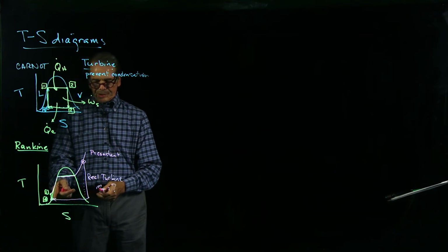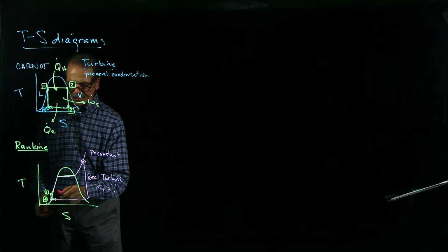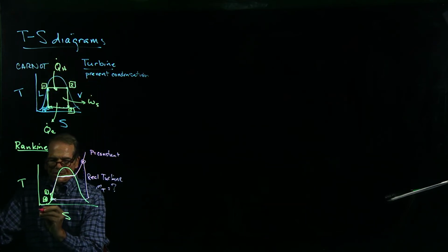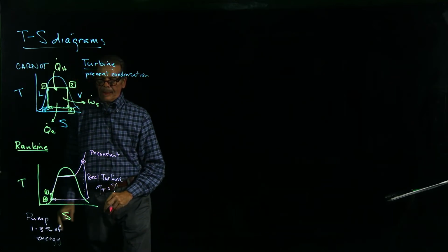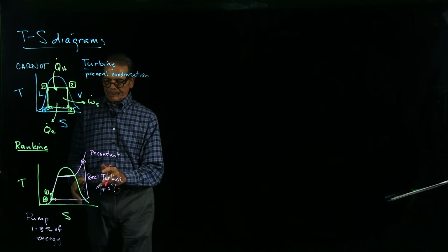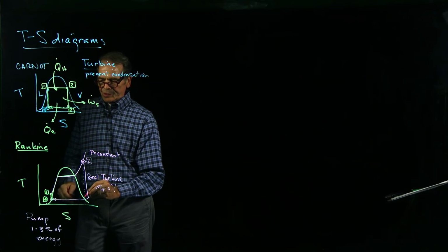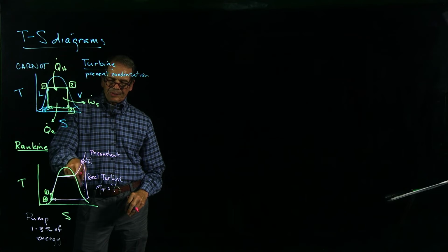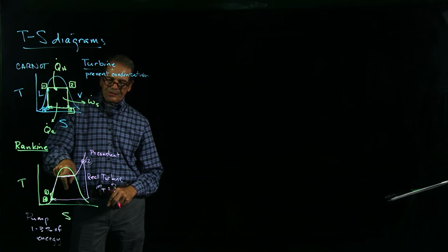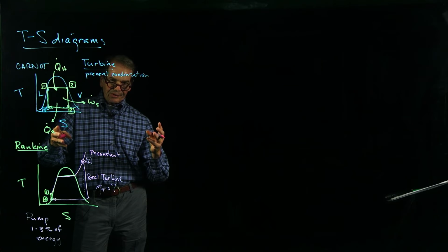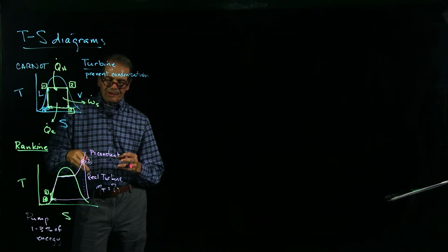The pump. We're going to put some energy into the pump, but this is typically only about 1 to 3% of the total energy in this system. Okay? Well, that's pretty good. Let me label the points. This is 2. So in the furnace, we're going to pump it up to a high pressure. These 2 pressures are the same. Pump it up to a high pressure and then change the temperature. So that's how we're going to calculate the change in enthalpy and entropy of the fluid.